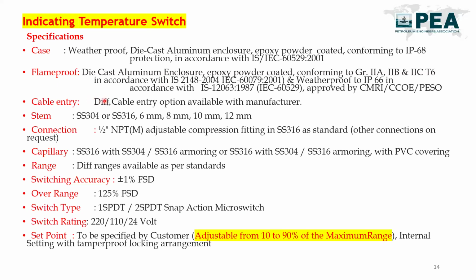Okay, so different cable entry sizes are available with the manufacturer. Stem length, stem, connection size, capillary, ranges. The temperature switch range we will select as per our high and low values. The range will be selected in such a way that our low alarm value and high alarm value come within 10 to 90%.